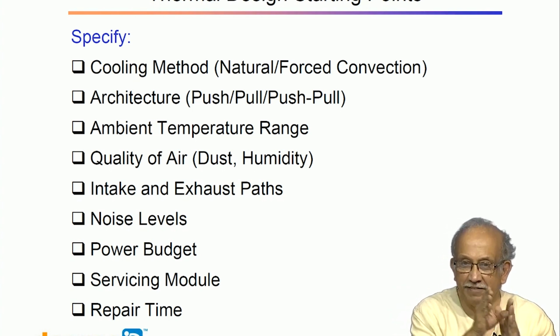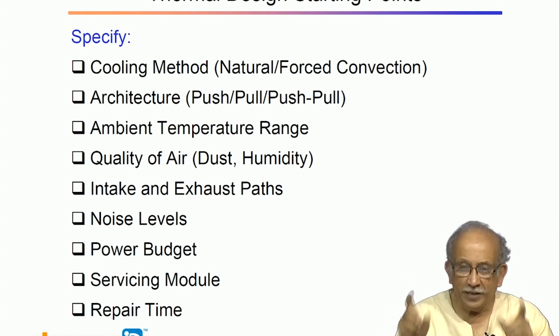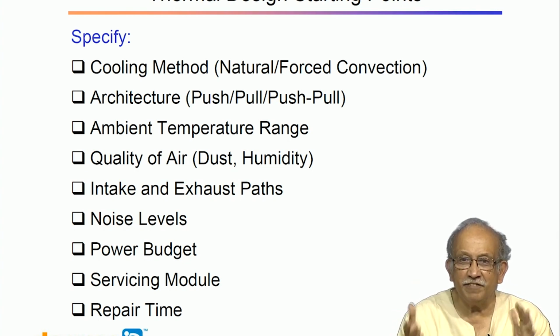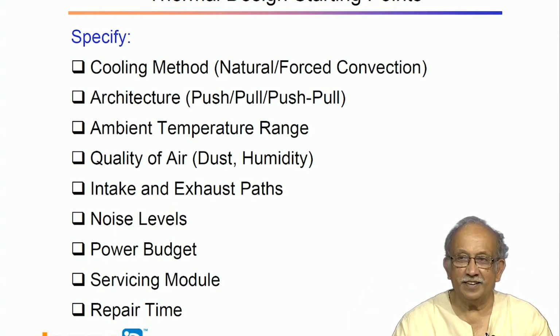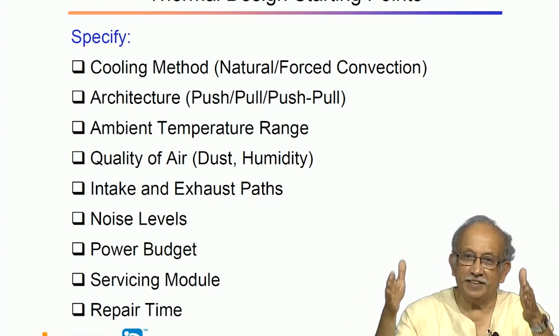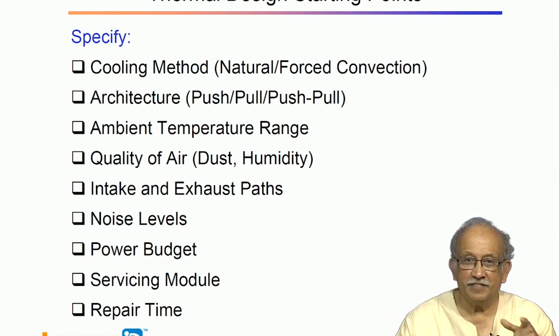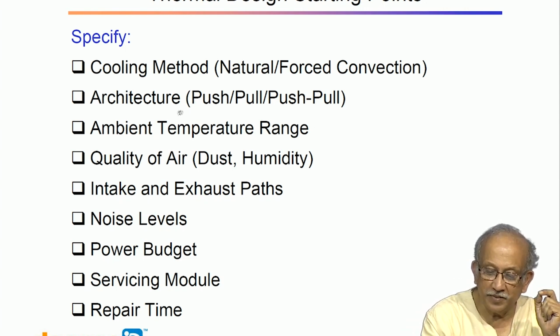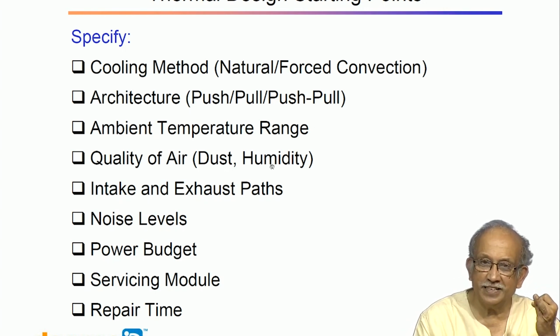Even in spite of having the best polyurethane formed in place insulation, still condensation is real. So, they have found out a much easier way. They run the condenser coils inside, which has a double benefit. You have much more area for the heat to spread, and it also aids in anti-condensation. So, we have this stuff about how to control the quality of air. You remove dust, you control humidity.